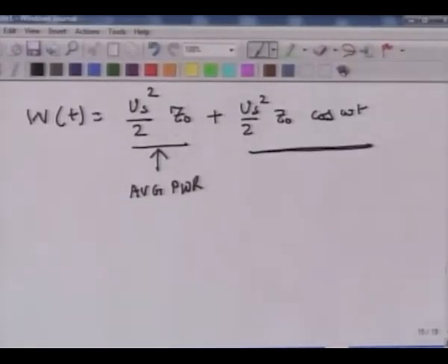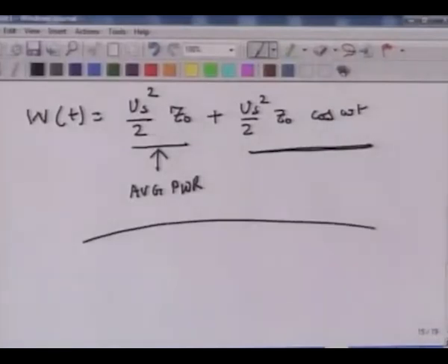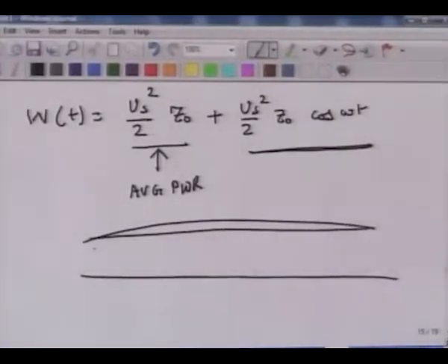So in a closed tube, we saw that because all the energy gets reflected by the closed end surface, the consumption of power by the source is 0. But here, because you have an infinite tube, and if I am exciting a membrane back and forth, that energy keeps on traveling and never comes back.